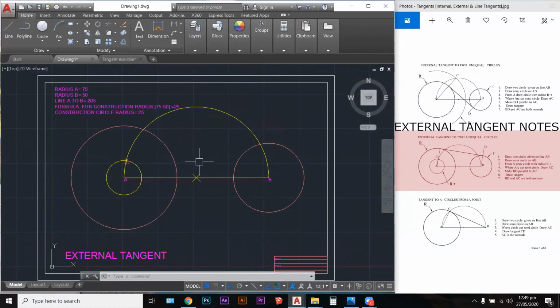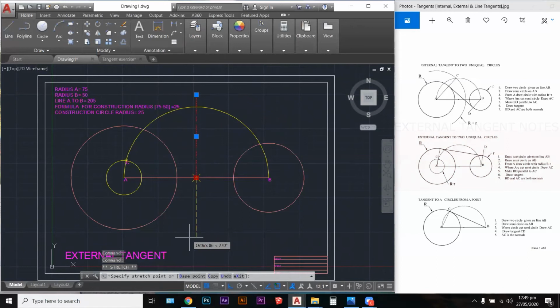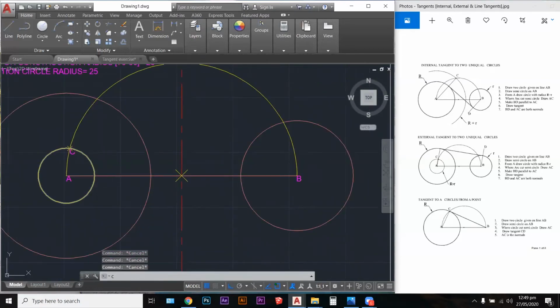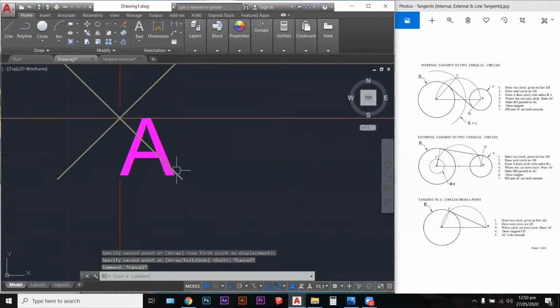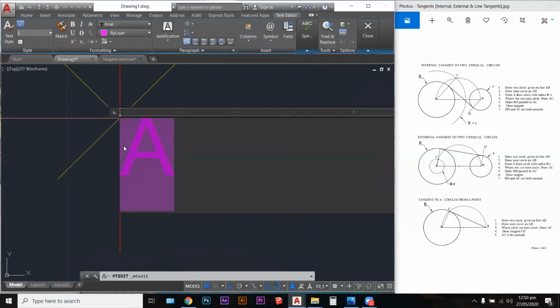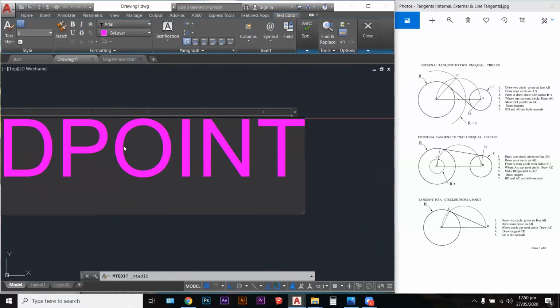So I'm going to create a center line so that if people are just watching this, they can understand what happened there and why I chose that particular point. This means the center. So this line is a center line. Whenever this line is used, that indicates that you're cutting something in half, or you're going through the center of something, right? I'm going to also label that. So I'm going to transfer the text from this point to that point, which is just simple copying and pasting. And then I'm going to go into the text box and type the word midpoint.